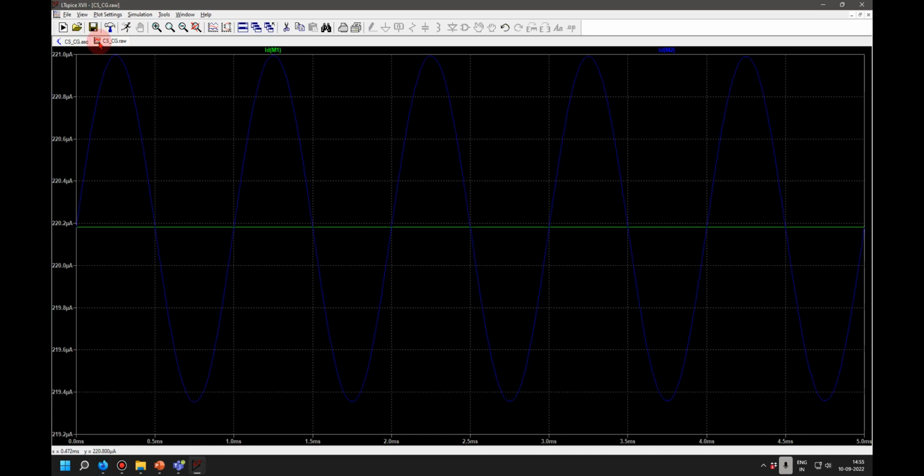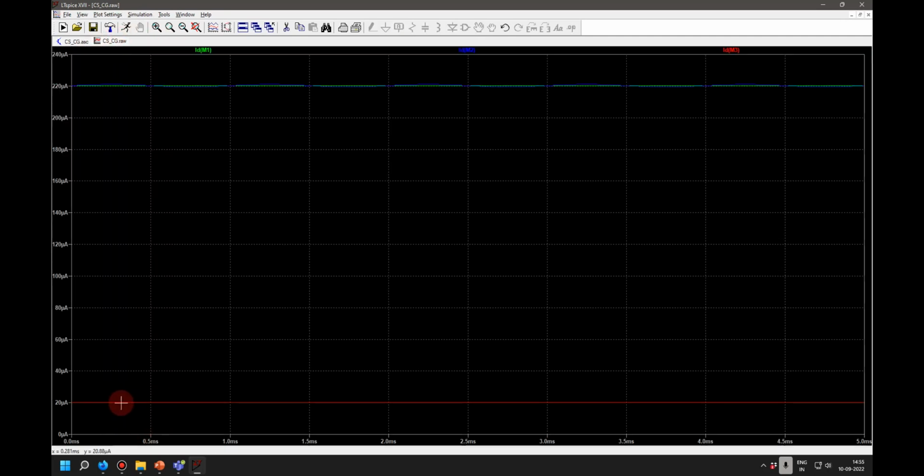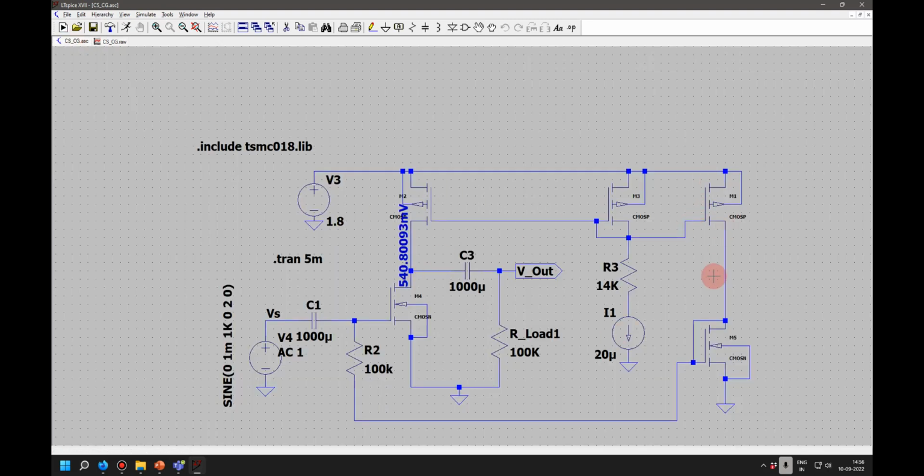If I plot this current, it will be 20 only, right? See, this is 20, whereas the currents there are 200, around 10 times. It is slightly more than 10, okay, because of the channel length effects, and we saw that we have those VDS issues also. So there are some systematic errors. So what is the voltage which is generated here because of this particular circuit?